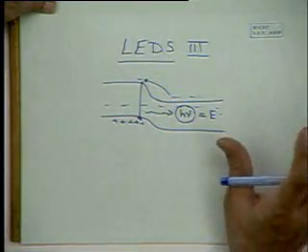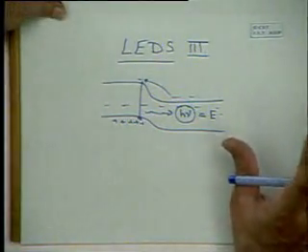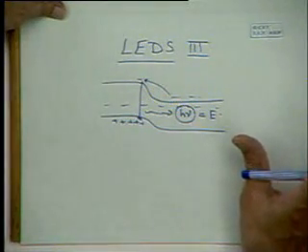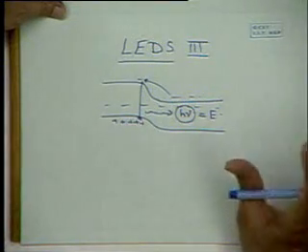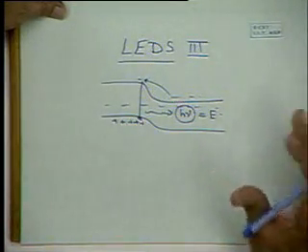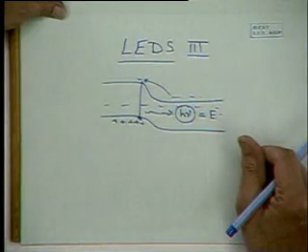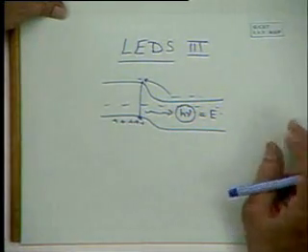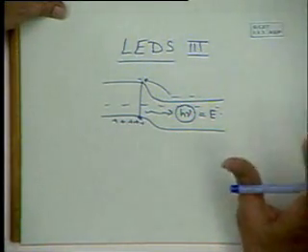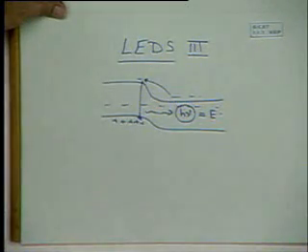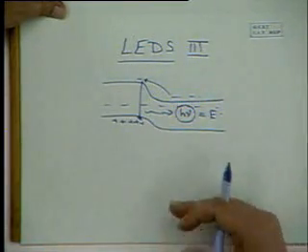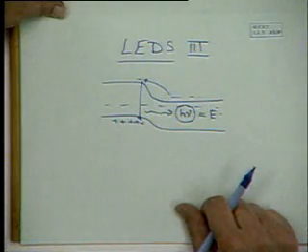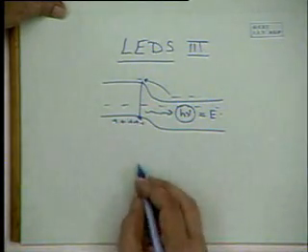I've already discussed that there are two types of substrates, transparent substrates and opaque substrates. Opaque substrates are gallium arsenide based, which absorb radiation because h nu is greater than Eg, whereas transparent substrates are things like gallium phosphide, which can reflect the light back to the top.